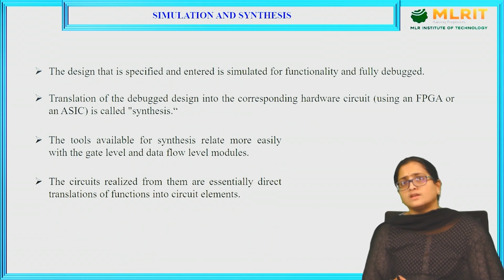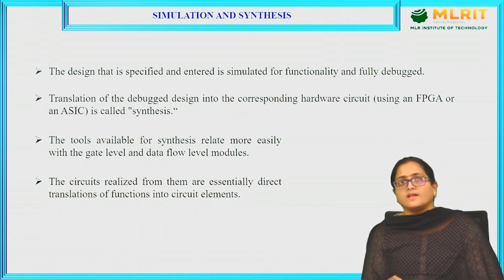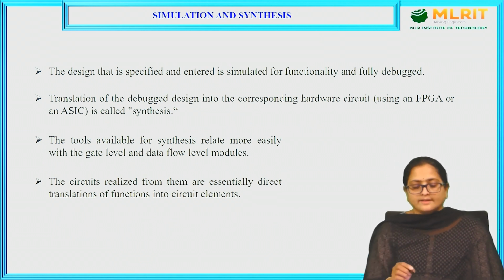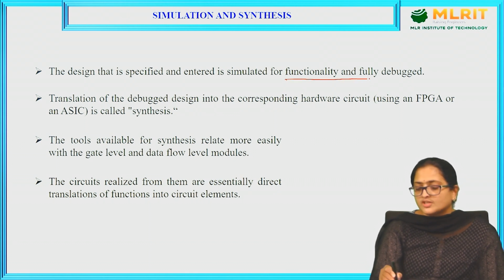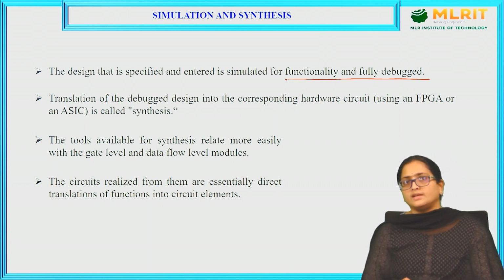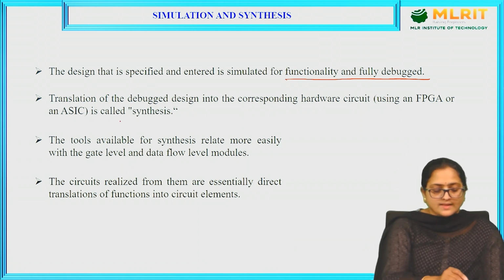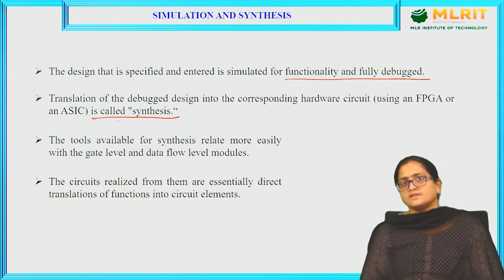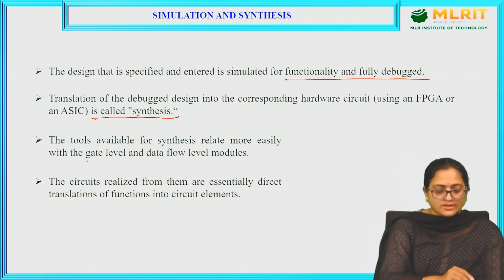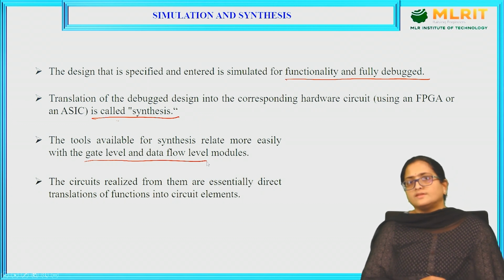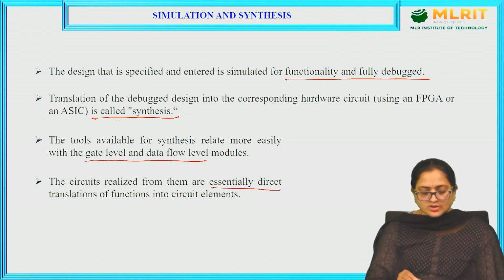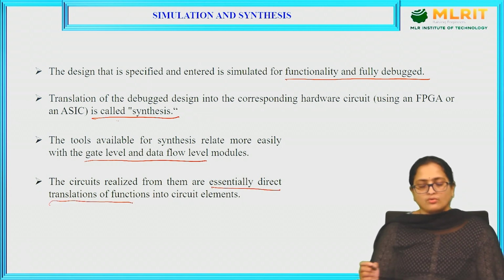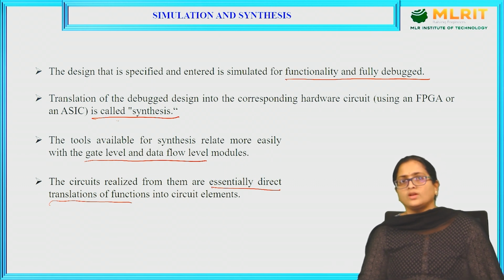The next one is simulation and synthesis. The design that is specified and entered is simulated for functionality and fully debugged. The translation of the debugged design into the corresponding hardware circuit is called synthesis. The tools available for synthesis relate more easily to the gate level and data flow level. The circuits realized from them are essentially direct translations of functions into circuit elements.